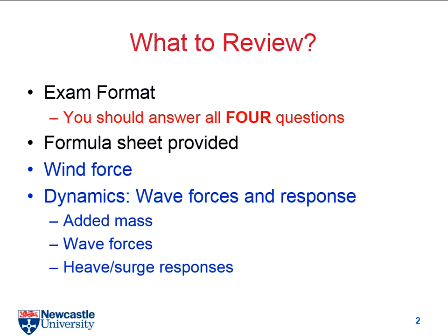But anyway, it's very straightforward, right? After you know the density, you have a drag coefficient, you have wind speed, but when you try to find out the acting area, according to different rules, we have different methods. And if you can still remember, I showed you 2 different rules. The first one is the API rules, and the second one is the example from ABS. So by different rules, we have different methods to calculate the acting area. But now, please just forget the ABS example, because in most cases we use API. But in your work, because you are going back to probably different ship societies, you will have different rules. But here is the most typical one.